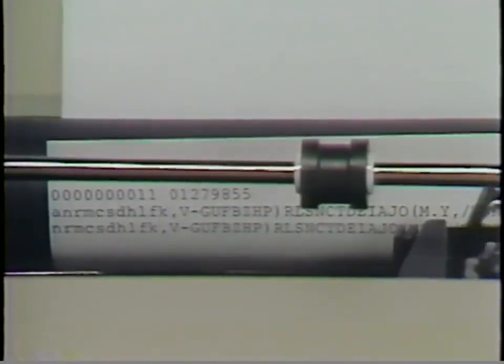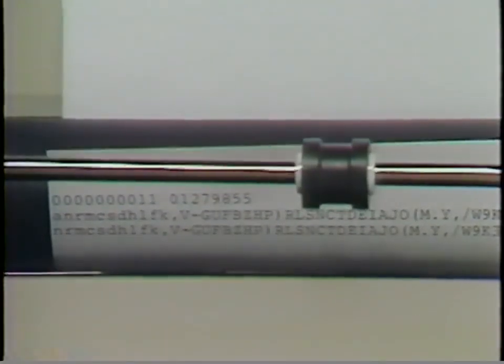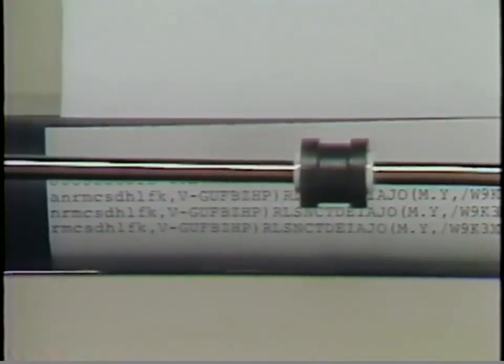The first line of the printer self-test provides information to the operator. The zeros and ones making up the first group of characters show the dip switch settings. A 1 means the switch is on, and a 0 means the switch is off. The numbers on the right identify the engineering level of the function board. The remainder of the printout is a continuous type sample of all the characters on the print wheel.